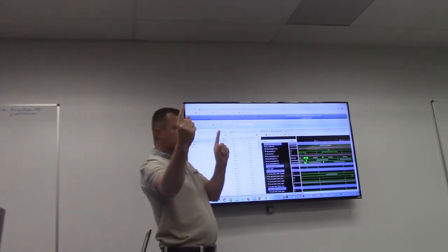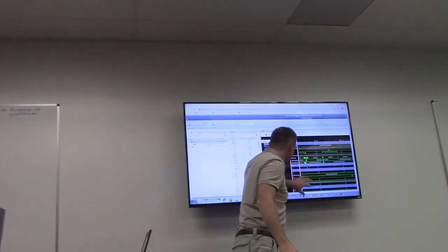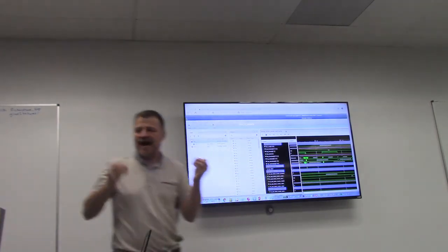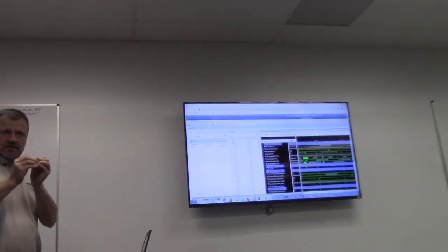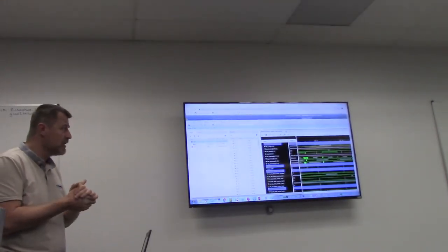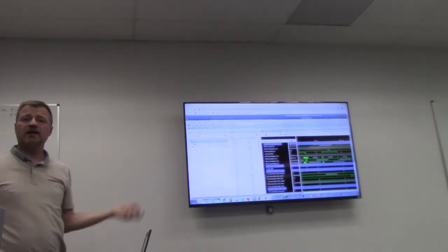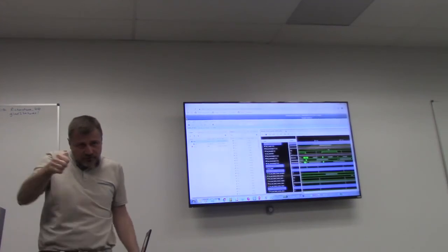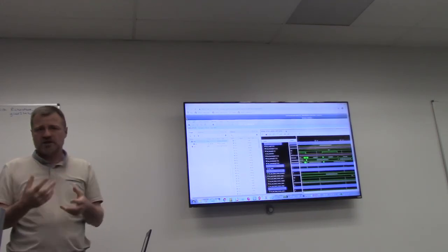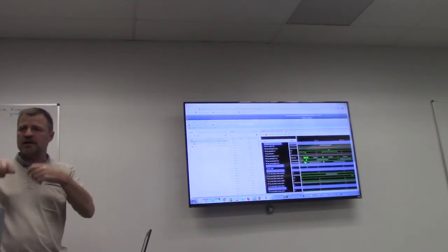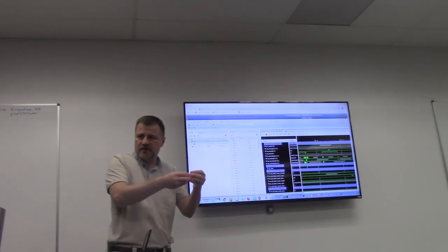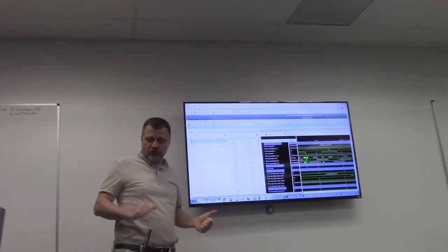So I can measure exactly this time, and because I have the clock here at the top somewhere, I can measure exactly how long it takes in the hardware. This will not take into account the actual CAPI link timings, but what Lance, our colleague, has done, and this is a very, very nice job, the CAPI modelization is also making the packets in different orders. You can select that you want the packets in the same order because it's easier when you debug. And then when it's working, you say, okay, now change the order of the packets and so on. So you can really debug even the CAPI link a little bit, not in hardware, but the overall behavior of your CAPI link.